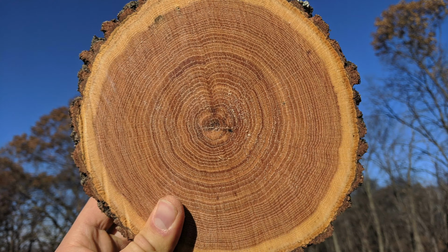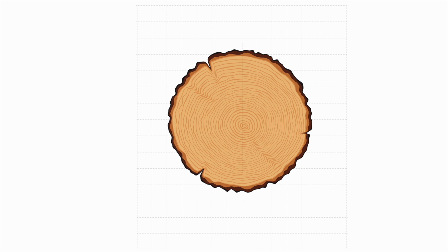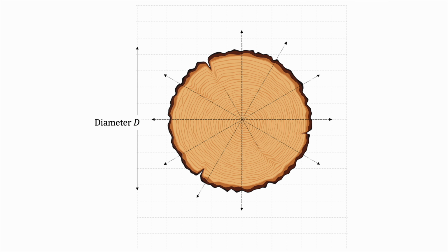Trees also have to deal with unpredictability in the direction of wind load, and this makes the axis about which a tree bends unknown. To address this variable loading scenario, trees have evolved a remarkable solution: having an almost circular cross-section of the trunk and the branches. Due to its symmetry, a circle is the only cross-section that has the same moment of inertia about any axis that passes through its centroid in the horizontal plane. This characteristic of a circular cross-section enables a tree to resist laterally acting forces such as wind load or earthquake load acting in any direction.